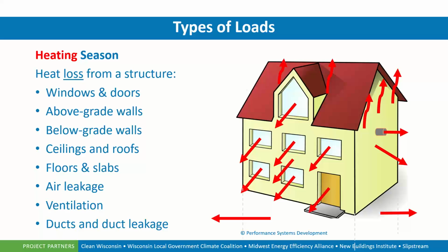We need to take into consideration ventilation practices, whether it's spot ventilation for bathrooms, how much does that contribute? It's not really addressed in a Manual J for bathroom ventilation that runs only when there are occupants in the bathroom. But if we have continuous mechanical ventilation or whole house mechanical ventilation, then that needs to be taken into consideration. Because in theory, we're exhausting conditioned air to the outside intentionally. Then we need to be bringing in unconditioned air into the system as a makeup. And how much do we actually lose through our duct system, whether it is from duct leakage or from conduction through the system itself?